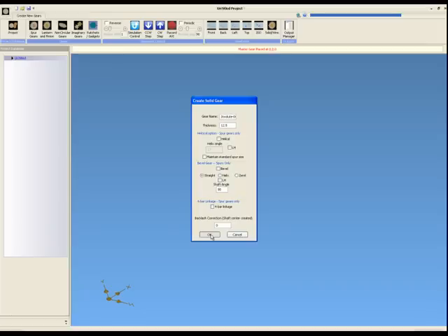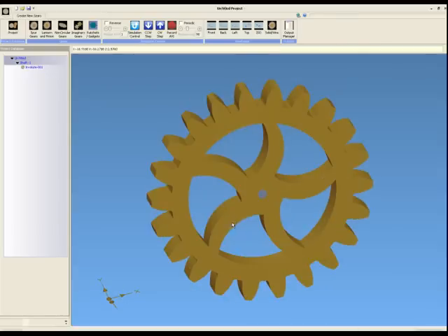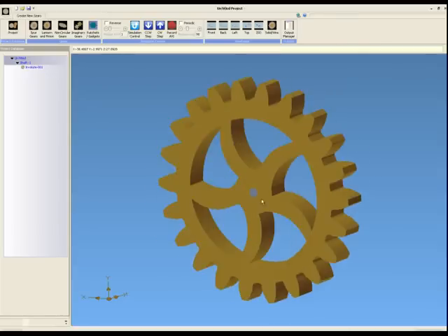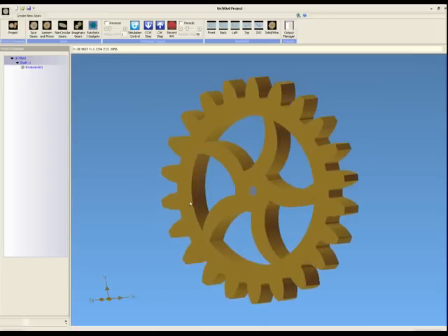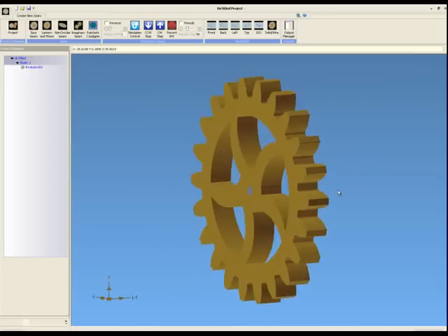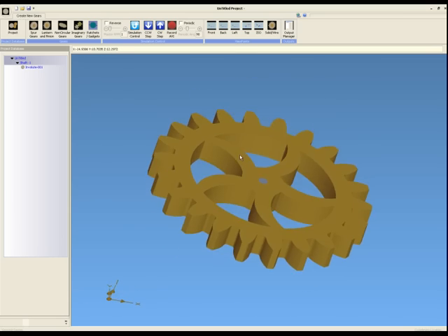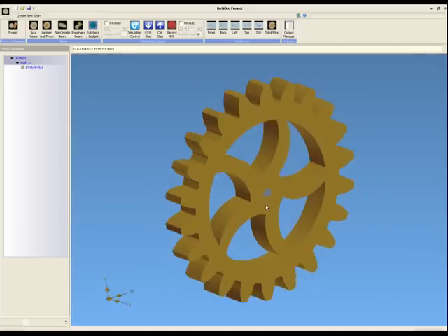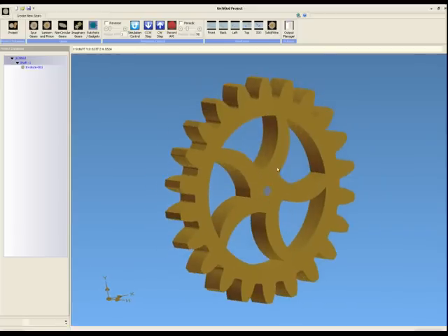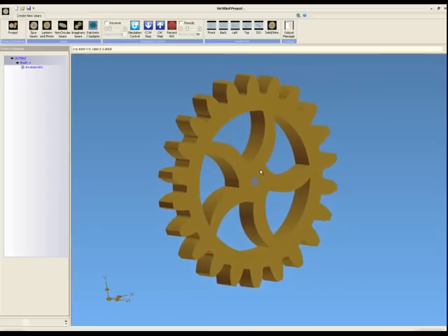Built as specified on the screen that we created. And as you can see, we now have a gear screen. I can rotate this gear by pushing the middle mouse button, or as of version 2.0, I can hold the Shift and Control key at the same time as my left mouse button and rotate the gears. This latest change is to facilitate the use of laptops, which oftentimes do not have a center mouse button wheel. Both mouse buttons at the same time, left and right, allow us to pan a gear around the screen.